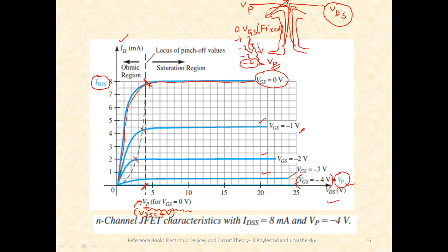if I just take a graph like this, that resistance, V equal to IR, so therefore R is equal to V upon I, and in this case it is VDS upon IDS. Okay, so if I just take a plot of VDS upon IDS, I'll be getting the resistance associated.